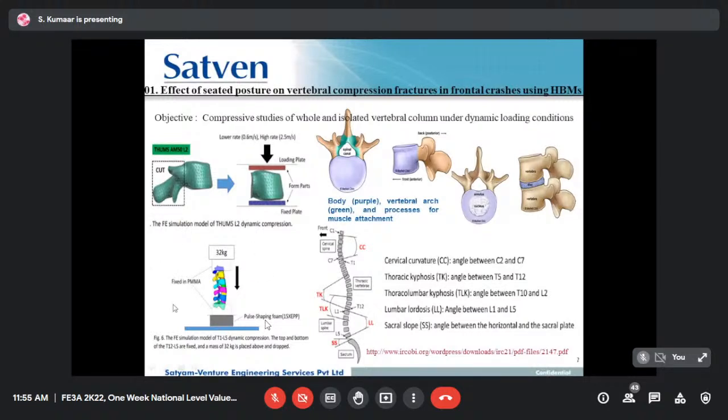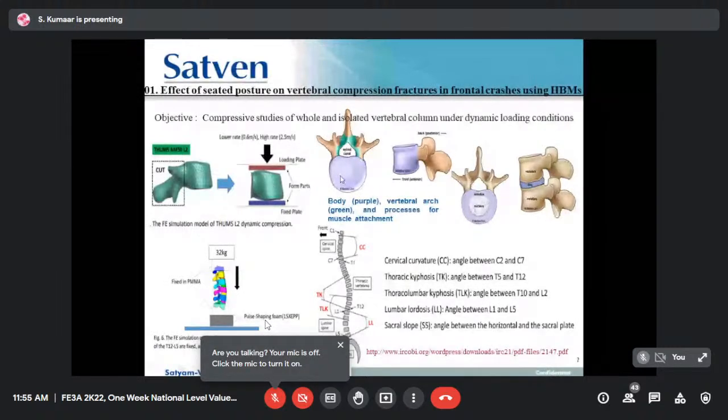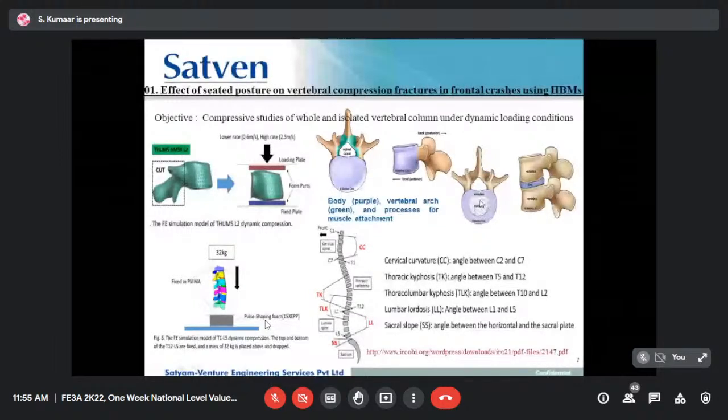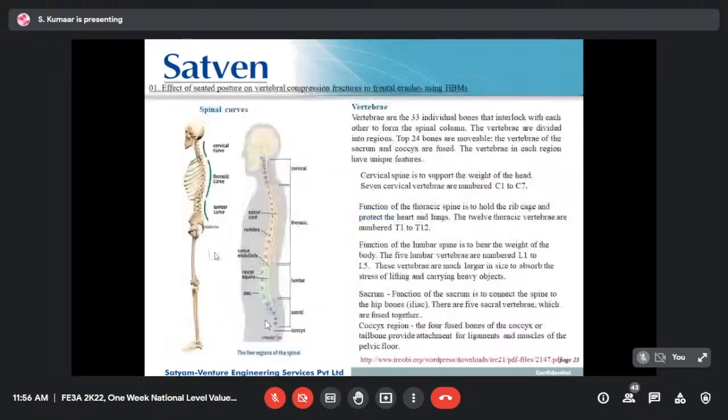Again we found some other papers with a different loading condition and a different setup. Based on this setup, again we need to perform iterations. Here, as we already fixed the material and characteristics for the vertebra, we will not disturb anything on that. Instead, we will be adjusting the nucleus, the annulus, the disc, and other properties. We need to correlate the simulation results with the test results. Once this is achieved, we will keep this model in our full vehicle simulation.